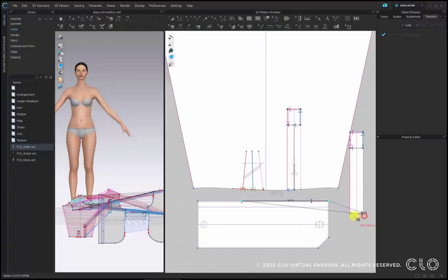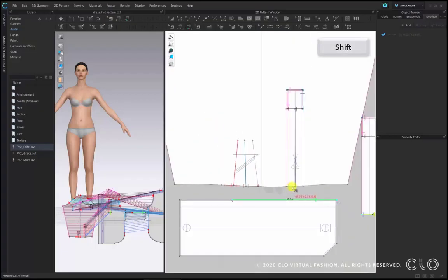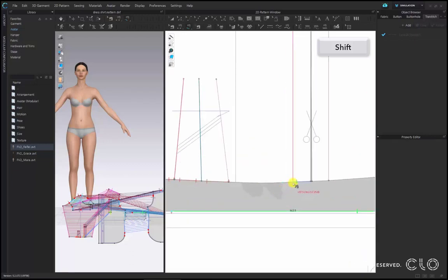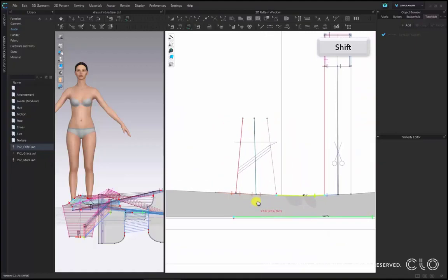And the first bit I have to attach is the little placket. Now I need to press shift to connect many sewing lines to one, just like we did before on the sleeve. And then I will start here with the internal line marked for the position of the placket until the first line that marks the position of the tuck.